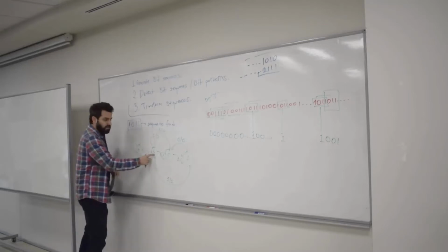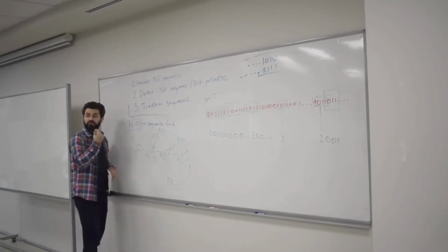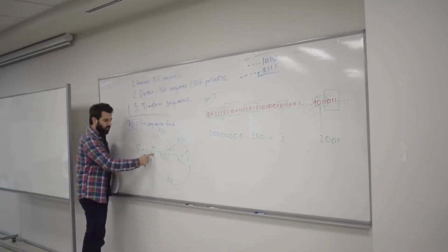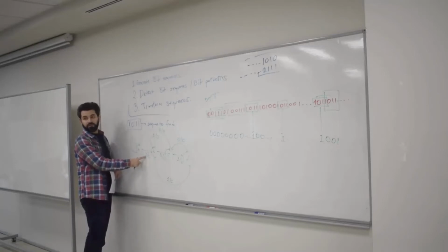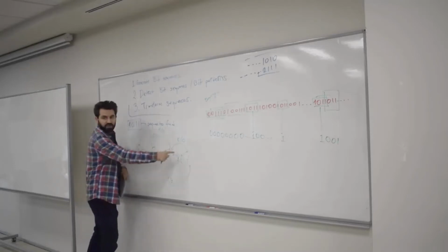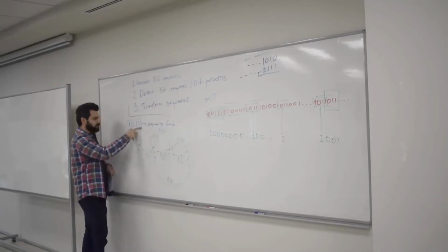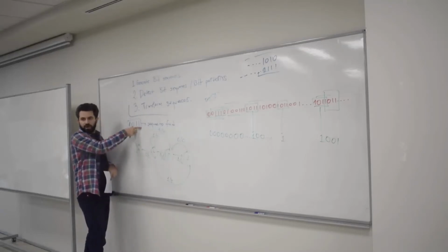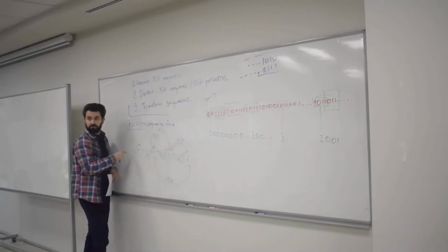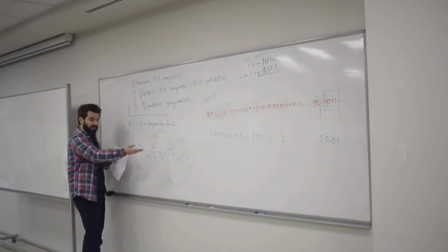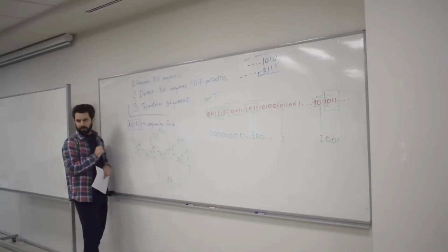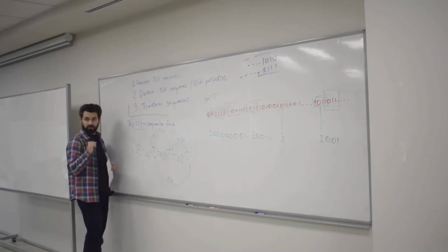When you're in state B, that actually means physically something. That means you already have seen a 1 in the input. That's why you're taking into your memory and counting whether this pattern appears in the input or not. Without that memory, you wouldn't be able to figure out that pattern. That's why we need a sequential circuit in the first place.